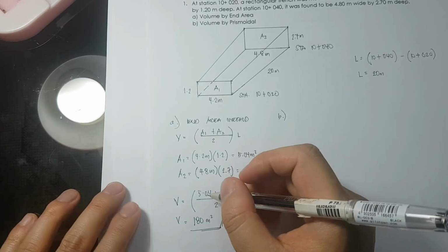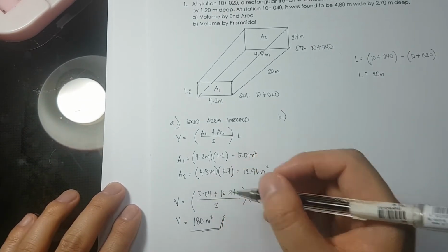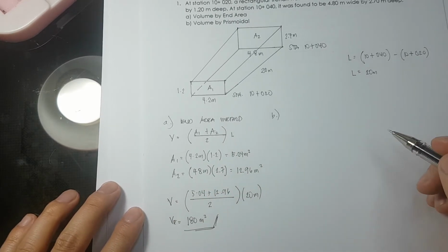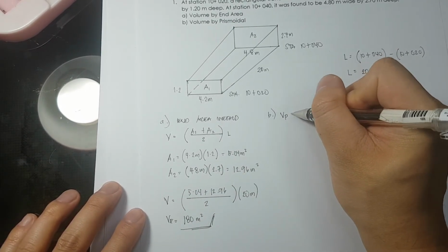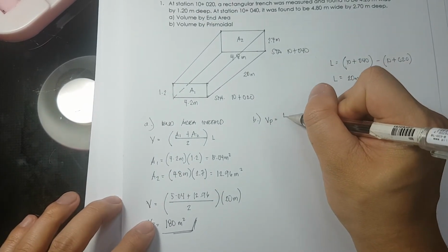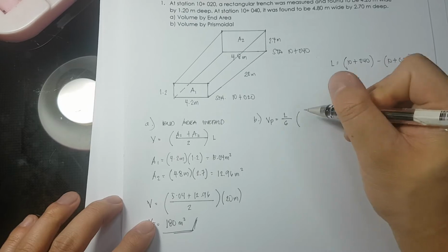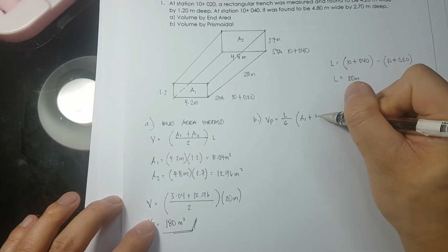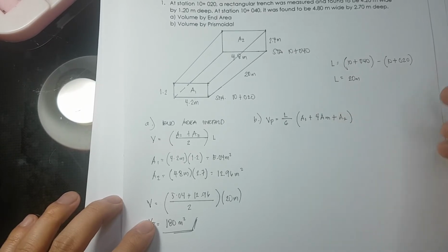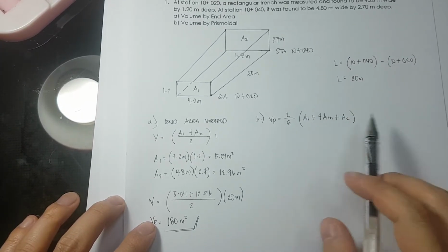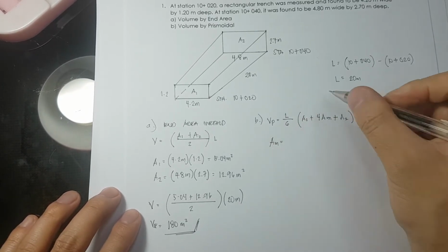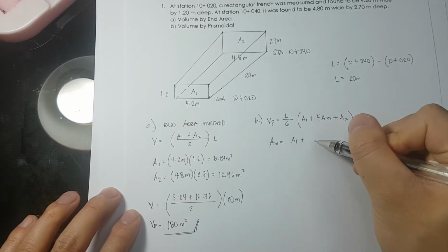This one is volume using the end area method, so let's say that's VE. Then for the prismoidal, that's VP. The equation for prismoidal would be L over 6 times (area 1 plus 4 times area middle plus area 2). So what is area middle? Area middle would be